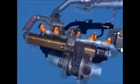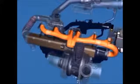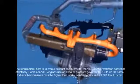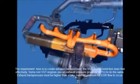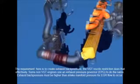Pressure inside the exhaust manifold is increased. This is accomplished through the use of a variable geometry turbocharger, an exhaust throttle orifice, or other restrictions. The recirculated exhaust gas enters the water-cooled EGR cooler from the exhaust manifold, where its temperature is reduced. The cooled gas then continues to flow through the exhaust tubing to the EGR valve.